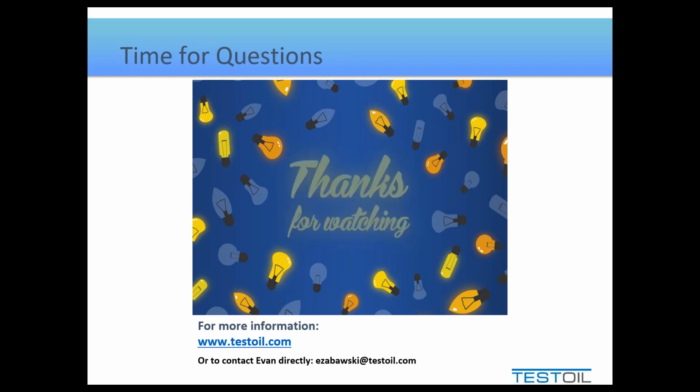Yes. And then looks like our final question for the moment. Mohammed also asks, how can we overcome the problem of not having hours on oil in the interpretation process? The easiest way to overcome that is to simply rely on the calendar. As long as samples are taken at consistent intervals, the assumption being the machine is operated consistently, not necessarily continuously, but consistently in the same interval.